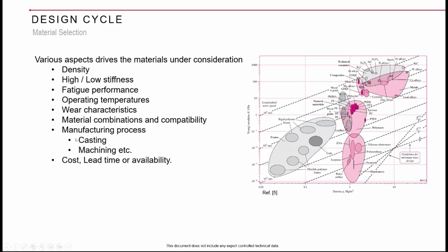Casting is another thing which you should be careful about, because the fatigue performance of cast parts drastically drops. I mean, it will be almost half of the machined components most of the time. So we should be careful about manufacturing processes also when you are selecting a process for arriving at your configuration at the end of the day. Okay, design may propose casting, for example. Then, as a structural analyst, I should come forward and say, hey, casting is not going to be a good fatigue performer, and we should be looking at machining or some other means to achieve it. Okay, something like that.